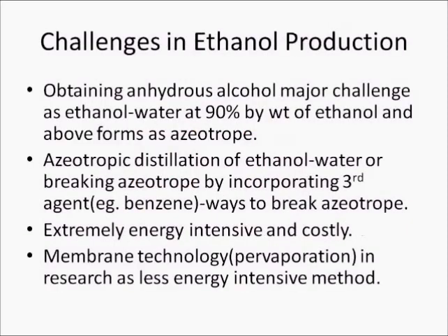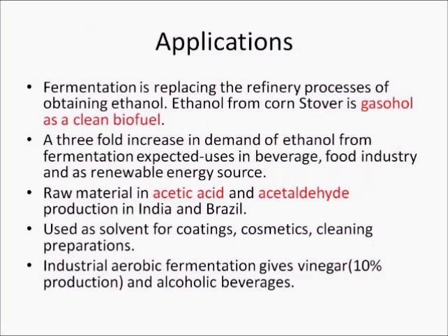In general, ethanol produced by any method needs to be purified to obtain a high purity and anhydrous product. The azeotrope of water and ethanol is a major challenge to be overcome, as breaking of the azeotrope either by distillation or counter-current extraction using another component is energy intensive. As stated earlier, ethanol is a versatile molecule and finds varied applications majorly due to good solvating properties, attributed to hydrogen bonding, potability, and calorific value.